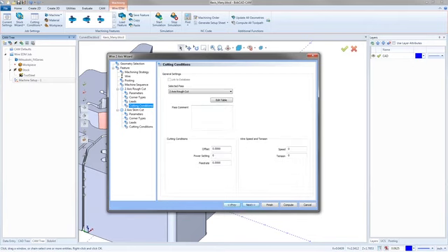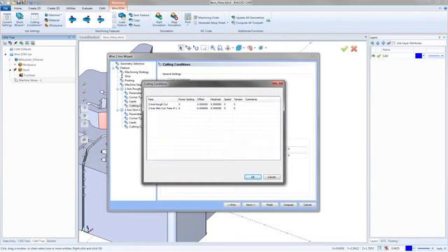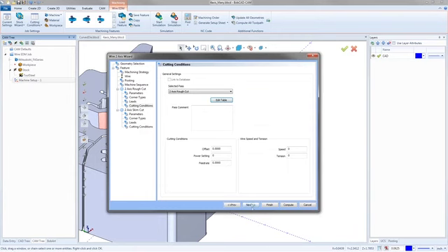Right here's the cutting conditions. I do not mess with the cutting conditions until I'm completely on the last page of the toolpath. The reason being, when I go in here, even if I know them, because I can go in and edit my table and start entering all my information, whenever you choose a rough and a skim, BobCAD only puts one skim pass in. So I'm going to hit OK and then hit Next.